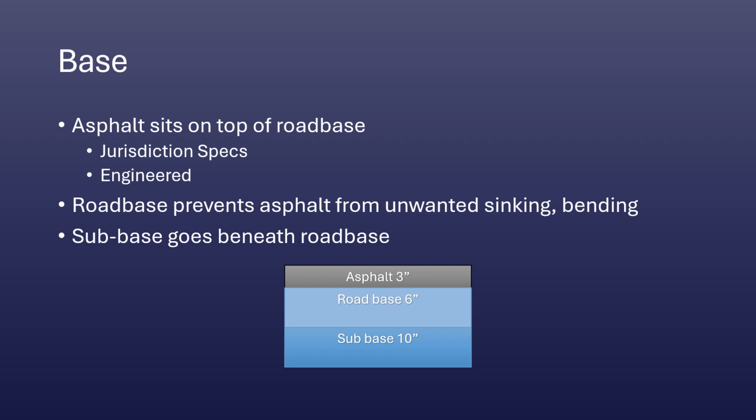And so where I live on the west coast of the United States, you'll see asphalt where water will come in underneath and it sits there for months and months, and then it gets really, really hot outside because of the heat of summer, and that water converts into steam, and it'll make its way through the asphalt, and that generates cracks.